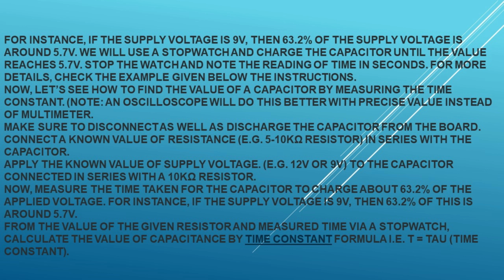Method 4. Testing a capacitor by simple voltmeter. To apply this method on polar and nonpolar capacitors, you must know the value of nominal voltage of capacitors. The level of voltage is already printed on the nameplate of electrolytic capacitors, while there are specific codes printed on ceramic and SMD capacitors. You may follow this guide which shows how to read and find the value of ceramic and non-polarized capacitors with related codes printed on it.